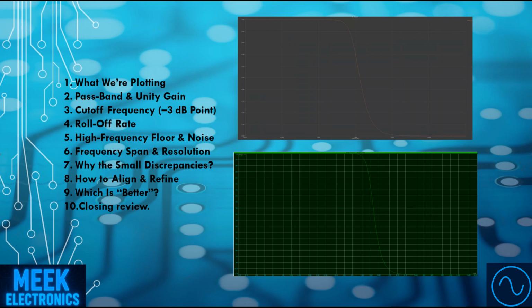Unity gain. In both tools, the passband is flat at unity. Proteus holds right at 0 dB. Altium sits at a gain of 1.00. This confirms the filter behaves as expected at low frequencies, with no attenuation or peaking.